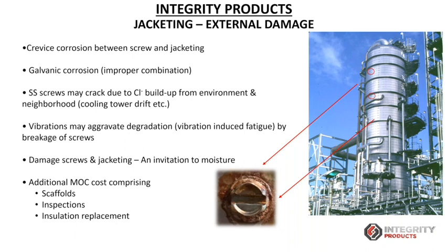And also in certain insulated systems, like on the reactor floors and on the regenerator systems in the refineries, there could be vibration in the system, and due to that vibration the corroded screws can break. Once there is a fracture in the corroded screws, the jacketing is going to be damaged from that location. It would be wide open, so we might see damaged insulation on the systems.